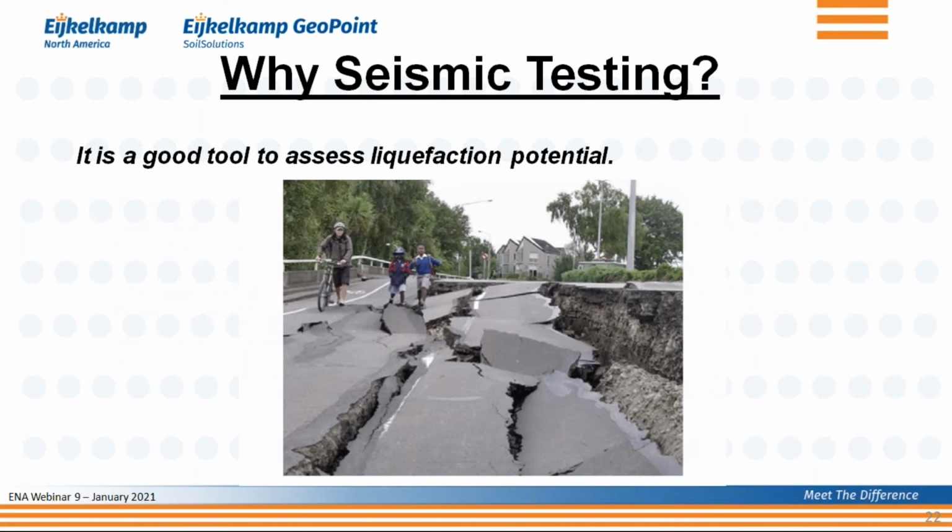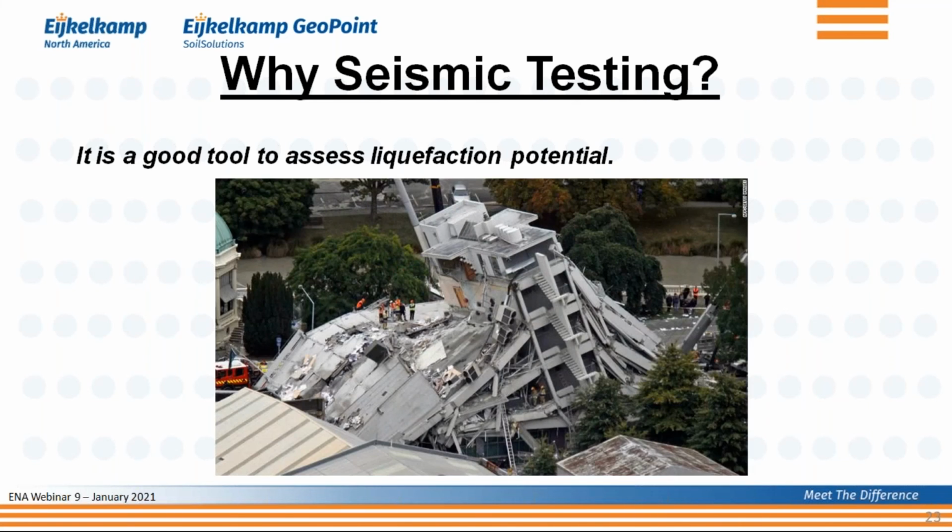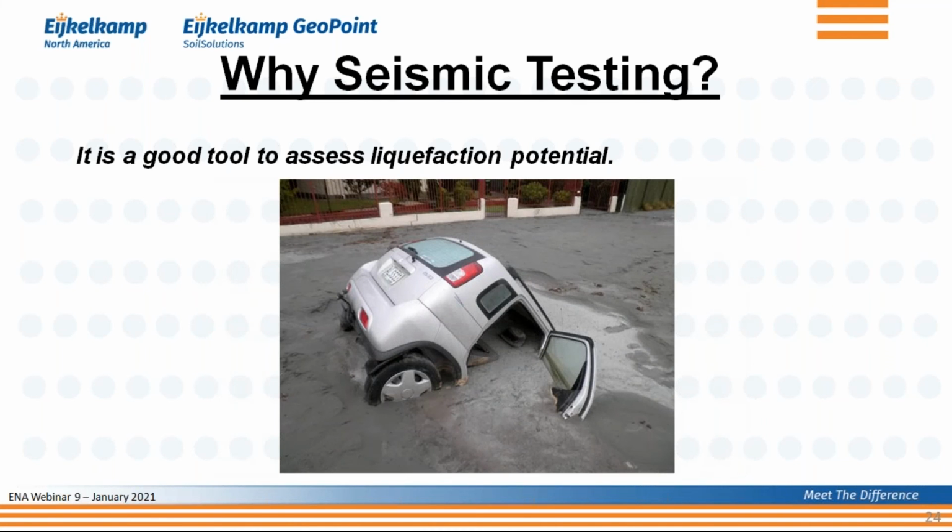What does liquefaction look like? Something like this. You have a road, then the earthquake basically liquefies the soil underneath it and it sinks down and you no longer have a road. Or when you have a building where part of the soil gets liquefied, no more bearing capacity, you get a situation like this. But my favorite picture when it comes to liquefaction is this one. You park your car, you go home, there's an earthquake, there's liquefaction, and when you come back, your car is kind of sunk into the soil, and it's hard to retrieve it there. You might as well say goodbye to your car.